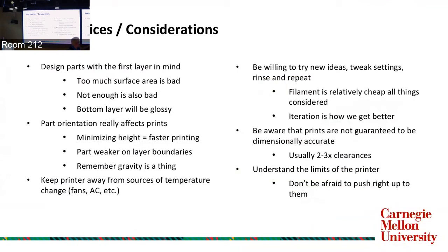And understand, this is what I was talking about, the tolerances, by the way. Understand that the printer does have really finite limits, but challenge yourself to push right up to those limits. I have wheels for this robot that are 2 layers thick and 1 shell out. So I'm thinking at the level of exactly what I can do with that printer, and I'm right up to it in the design.